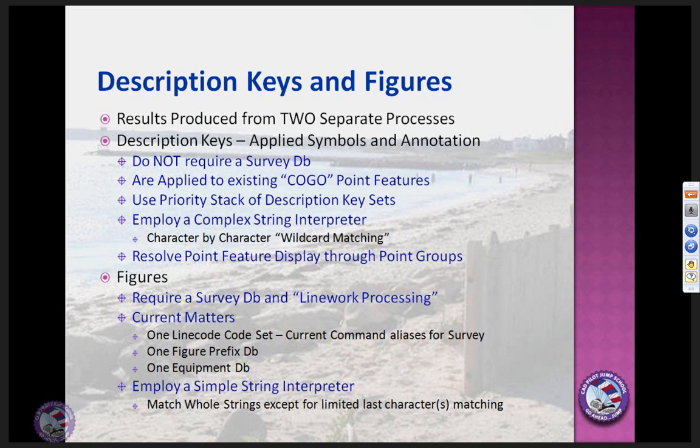So you will notice in point groups, there's a tool, apply description keys, so you can change up what you have. And once again, I pointed out the description key stack. Figures are directly connected to the survey data back there, and they require an open survey database to update to, one that's open, read-only or read-write. And they go through a line work processing routine.